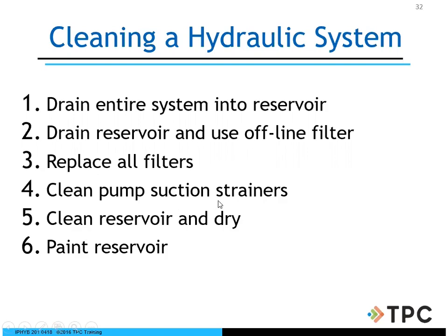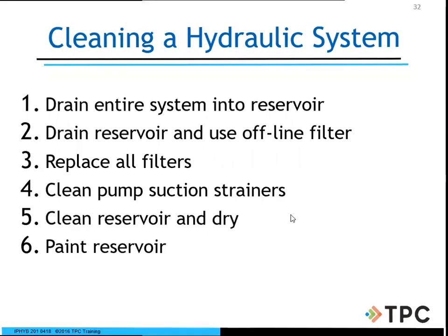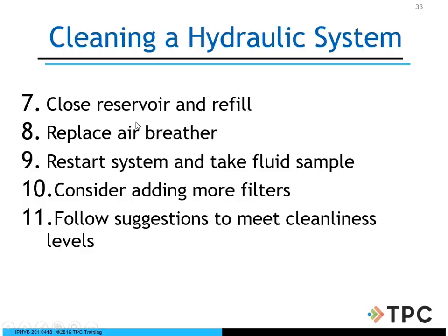Clean pump suction strainers, very important. Clean your reservoir, make sure it's all dry, nice and clean. Then on the outside, of course, you can make it look good and paint it and make sure everything is up to par, in a professional and workmanlike manner. Close the reservoir and refill, replace the air breather, restart the system, and take a fluid sample. Consider adding more filters if you really need it. Follow suggestions to meet cleanliness levels.